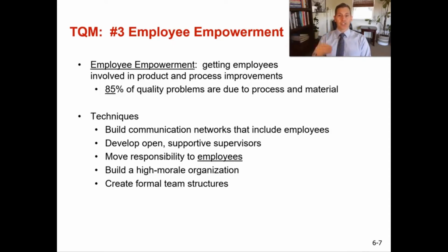And then they purchased blue, green, and red screws. So the employees could not make the mistake, or it made it far harder for them to make the mistake. When you're screwing in a blue screw, it better be going into a blue hole. When you're screwing in a red screw, it better go into a red hole. That is poka-yoking a process.